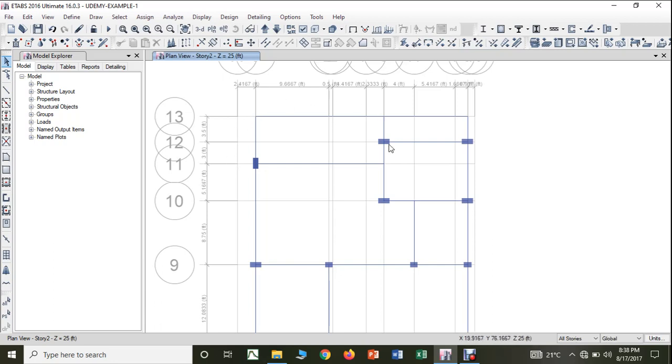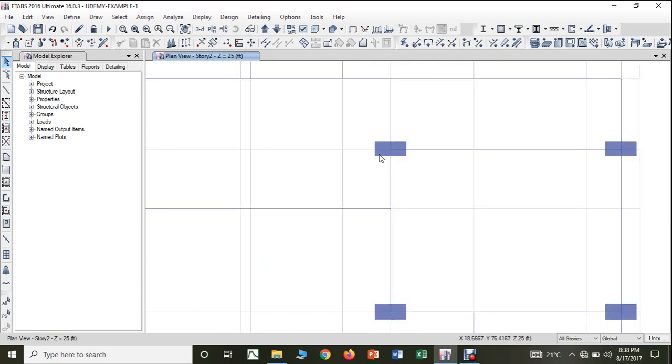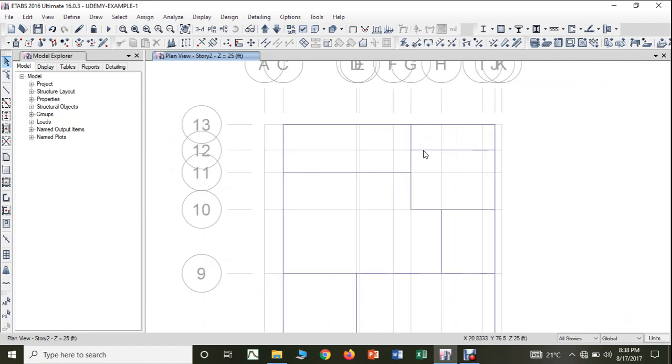Now similarly, in the same manner, here also it is better to change my orientation. Why? You can see this is my main beam, and this is also my main beam. But since there is a cantilever here, I had better change it. And not only that, this is the utility area. If I place it like this, then this part will come out from the wall, which is not good. So better I orient this, and I will change the orientation of this too.